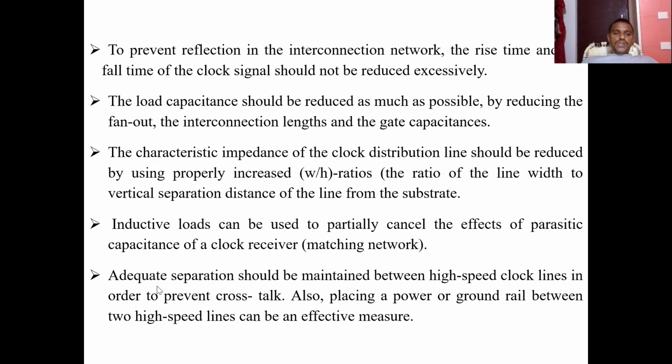Next, adequate separation should be maintained between high-speed clock lines in order to prevent crosstalk. So what does crosstalk mean? If you are talking on your mobile, suddenly the call goes to another person. That type of connection is called crosstalk. To avoid that, we have to use all these techniques.